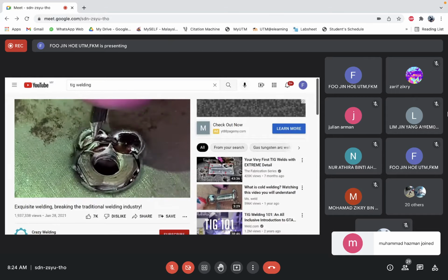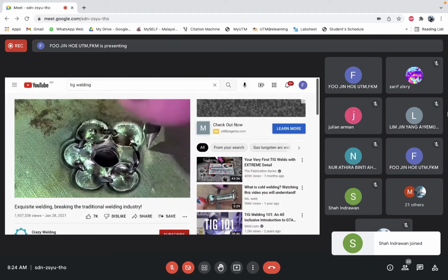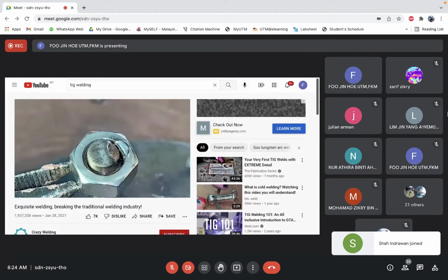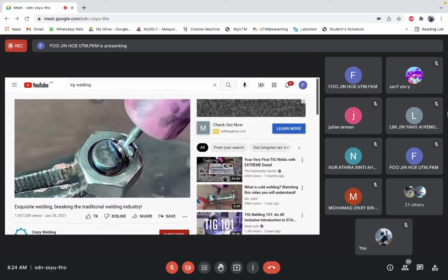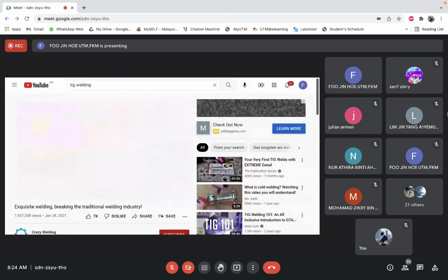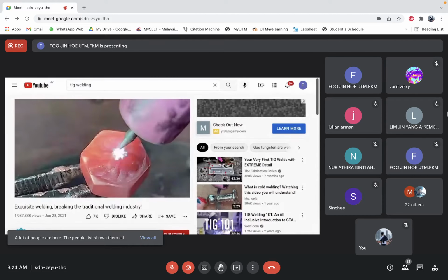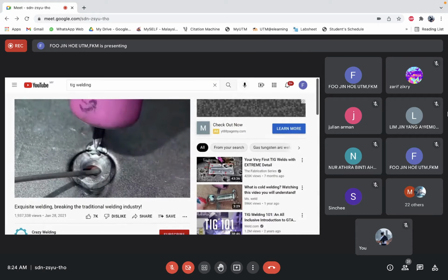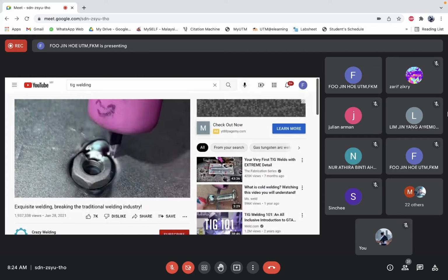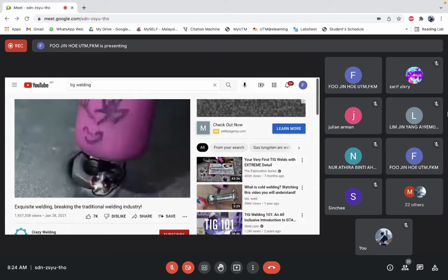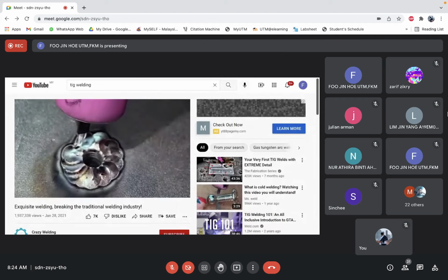Usually, the welding material is selected according to the nominal guaranteed value of the deposited metal, and the actual strength of the deposited metal is often much higher than the nominal guaranteed value. If the metallurgical factors or the fusion ratio are considered, the strength of the actual weld metal will be far higher than the nominal guaranteed value of the deposited metal of the welding material. Desire is low strength, matching reality may be equal strength. Desire is equal strength, reality may be super strong.